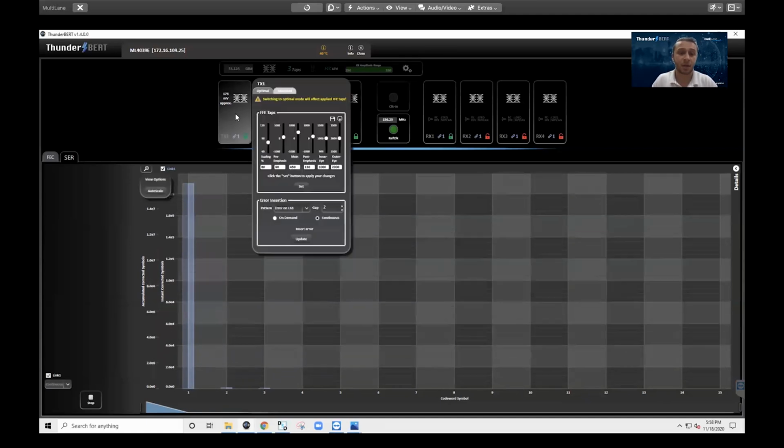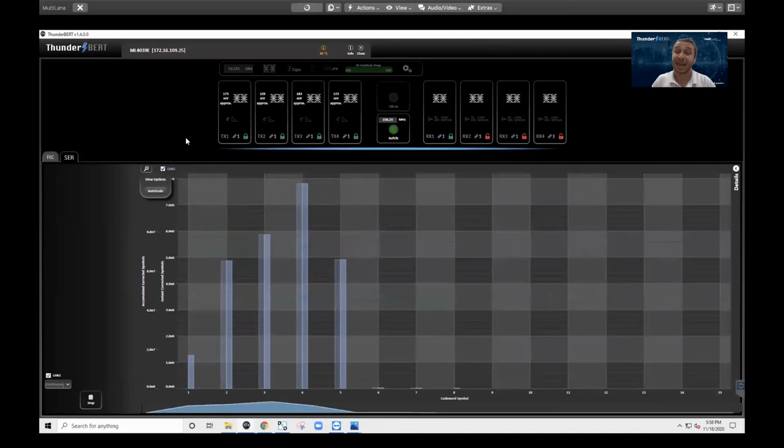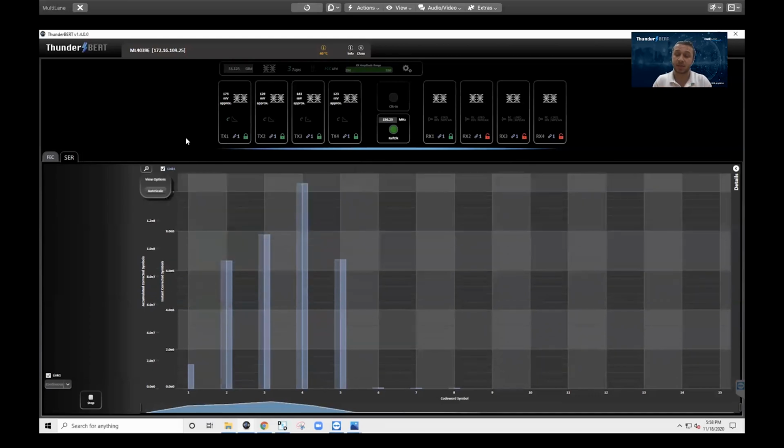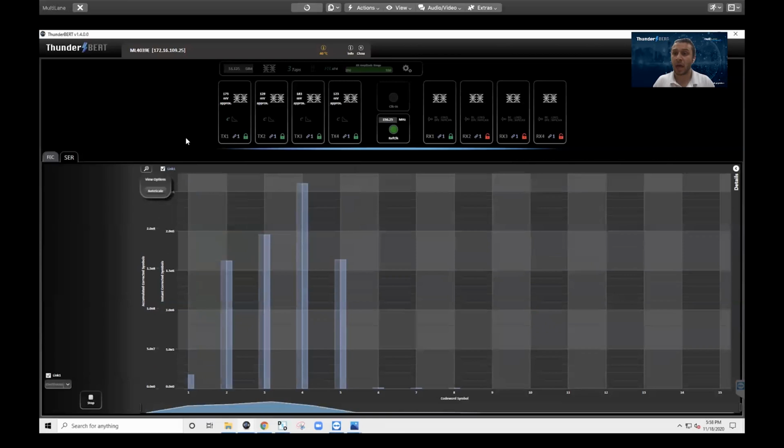And as a final touch, what we can do is inject some errors in the middle of this SER test. And now you can see that FEC margin has decreased because instead of only having code words with 1, 2, or 3 symbol errors, we have code words with 4, 5, 6, 7, and even 8 symbol errors. And that is an indicator that you're still okay, but you're approaching the failing edge.